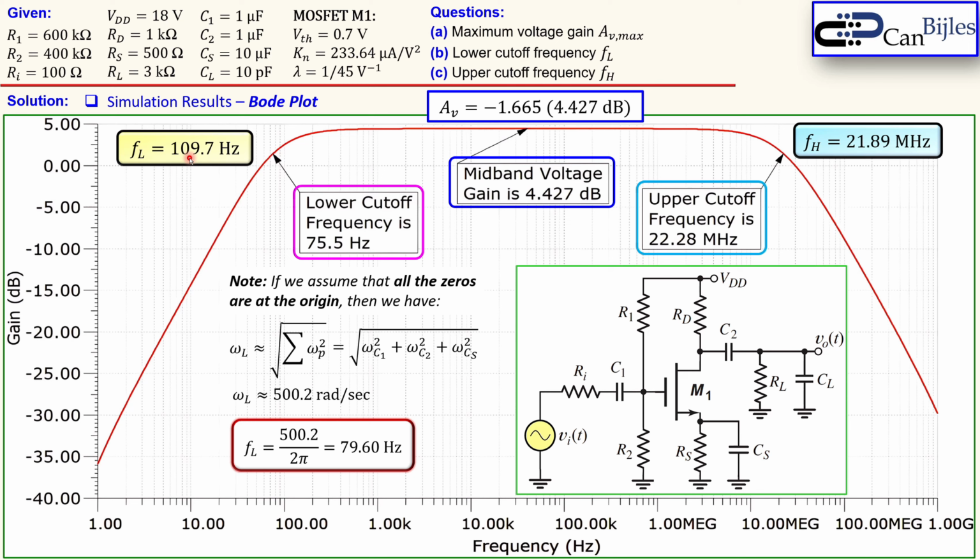Well, you might say, how do we know that beforehand? Yes, because the methods we are using are based on the short circuit time constant method and open circuit time constant method. Those are not exact methods, so they are using approximations, but it will allow us to move forward faster and then also see the picture which one is dominating and which one are not dominating. We have also seen that, for example, this omega C1 was the smallest one, and these two were dominating, so you can pinpoint which capacitor will actually dominate your lower cutoff frequency or the higher cutoff frequency. That's actually the advantage of using those methods instead of the exact analysis, where you see, of course, the complete and the actual expression, but it's of course not really intuitive and not design-oriented.